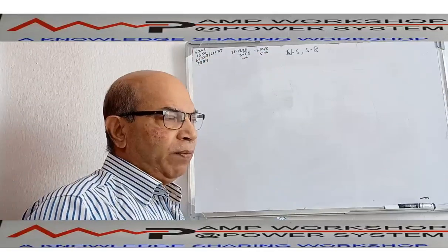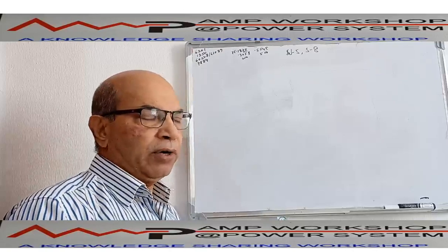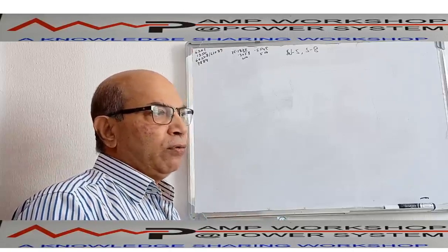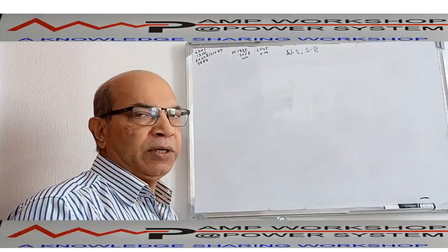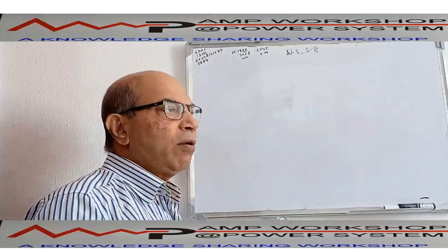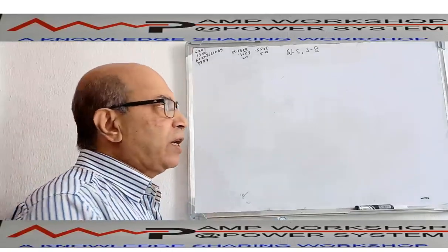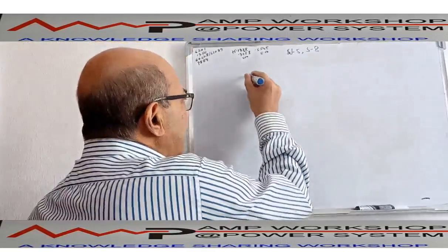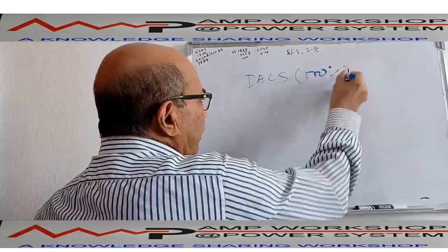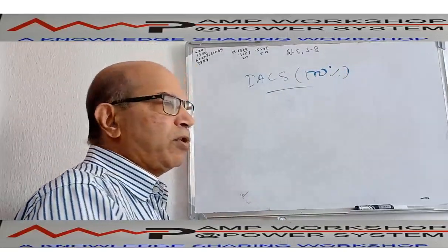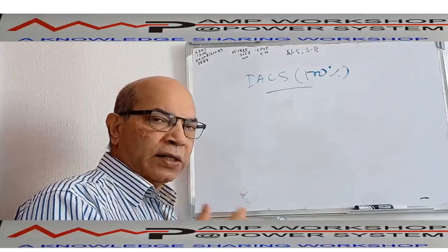These two materials are mainly used for overhead power purposes. The copper which we use is not the normal copper; it is called annealed copper. Annealing is a process of heating and cooling by which we change the copper properties. Its strength can be increased, its ductility can be increased. So we use that type of annealed copper for this purpose. As per the International Annealed Copper Standard, IACS, annealed copper is called 100% conductivity, and with this we compare the conductivity of other materials. Its mechanical strength is not bad.